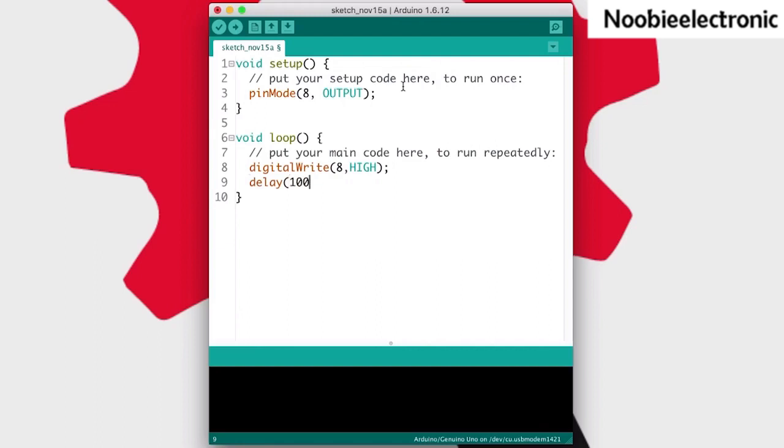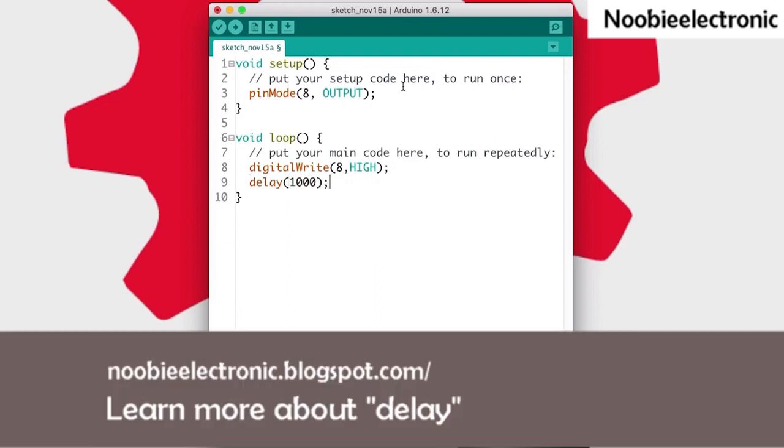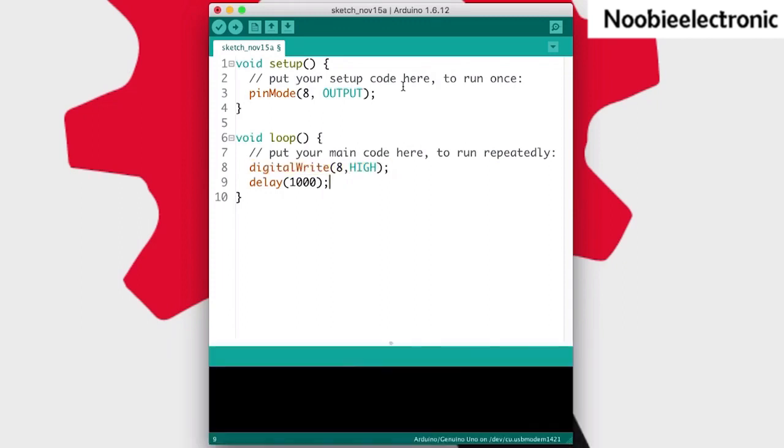Let's say 1000 milliseconds. The delay function allows us to insert a delay in our sketch. Whatever the previous instruction was, we are going to insert a pause here, and that instruction will remain as it is.